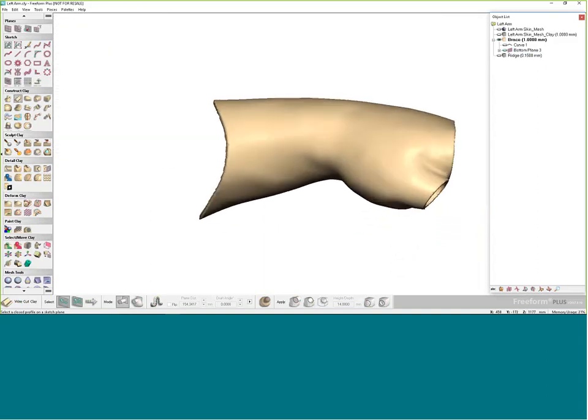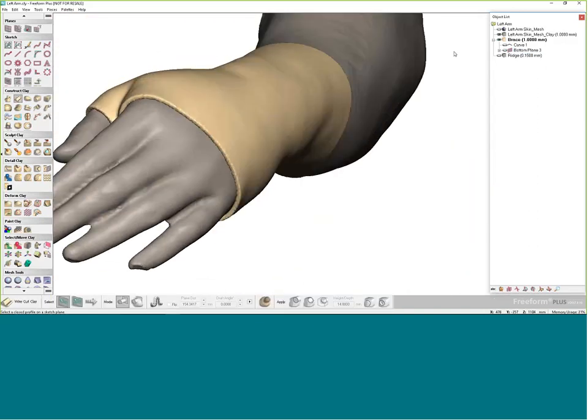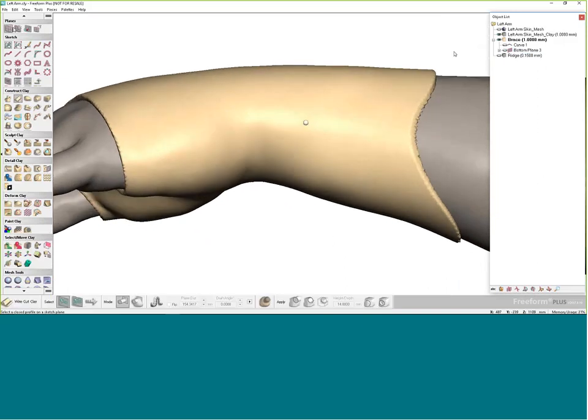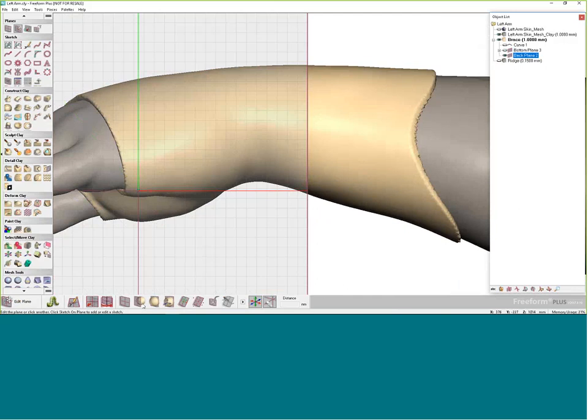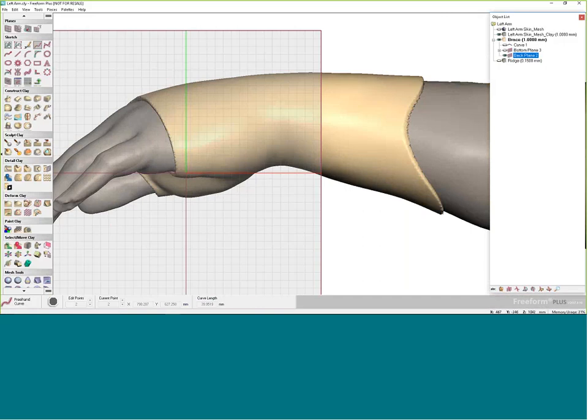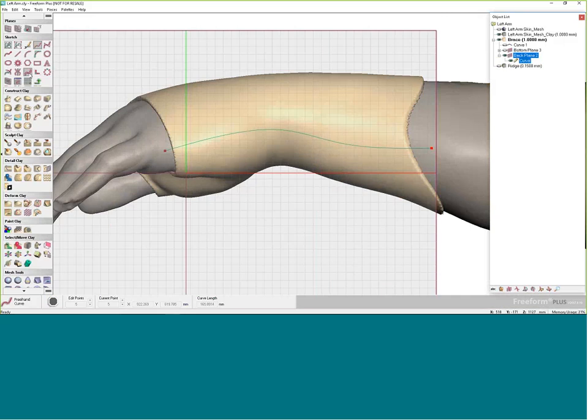So let's say that this person wants a two-part brace. He wants a top and he wants a bottom, and he wants them to be kind of unique. So we'll go ahead and create some parting lines on the side here. And again, we'll just repeat this process. I'll create a plane, make it normal to my view, and then I'll use this free curve here and create a unique parting line. And I'll offset that parting line by 2 millimeters. Just set it up, and then I will close this out so that I can use the wire cutting once again and make this cut.